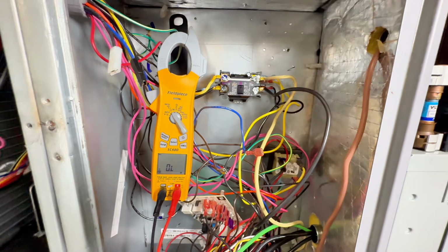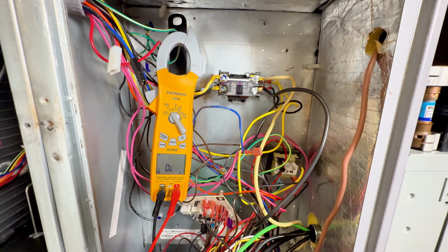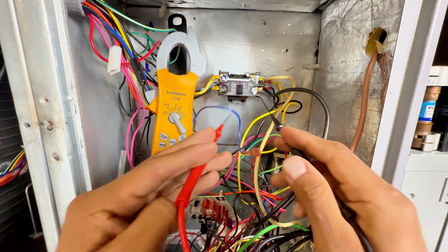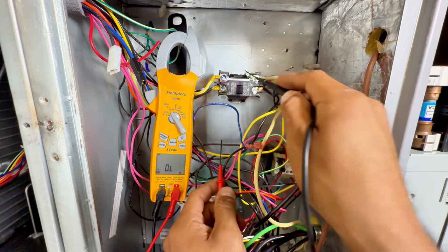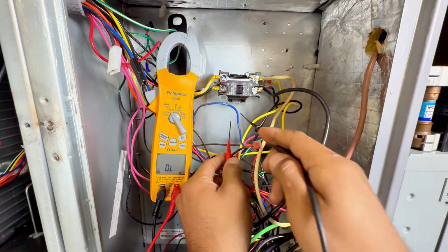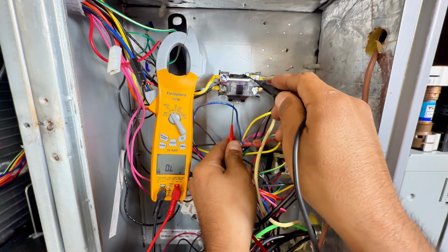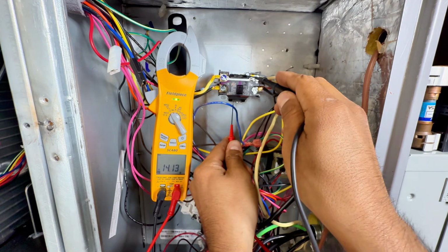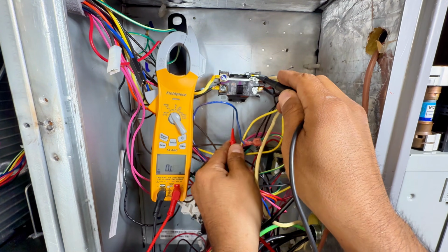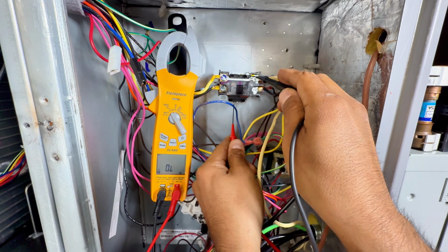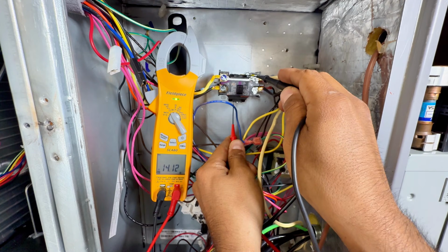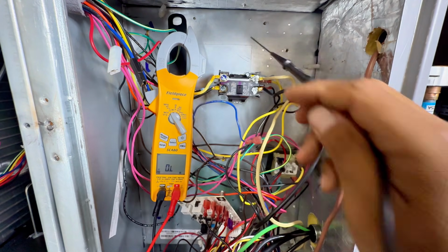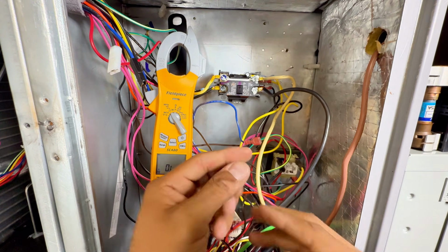Another thing too, from my experience, you want about 13 to 21 ohms of resistance when it comes to your coil, because this is a load. This can also be bad. So let's go ahead and test that. You see right there, I'm reading about 14 ohms. So it's still in good condition. But if you read open line, or you read like 5 ohms or 3 ohms or 0.5, then it's a bad contactor coil. So yes, schematics is one thing.